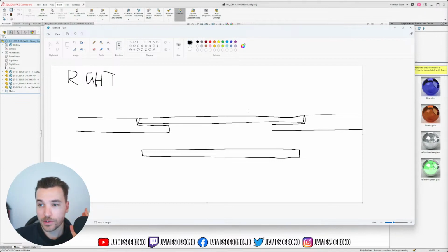And that just reminds me, I forgot to mention the second problem with the last design was that because it was shaped like this, it has to have this part cut out of the plastic. So you need to do that with like a CNC mill or something, which is totally fine, but it's an extra process that you have to do. And it's also something that has the potential to fail. They might not cut it down to the right height, or there might be some variance or whatever. It can be very annoying.